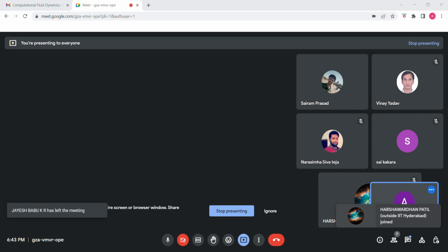It is given that you wish to compute the steady laminar fully developed flow field through a triangular duct as shown in figure 1. This is figure 1. For this case, it is asked which is the governing equation. So we will see that in general it is del dot u equal to 0, basically the conservation equation, we'll write it like this.